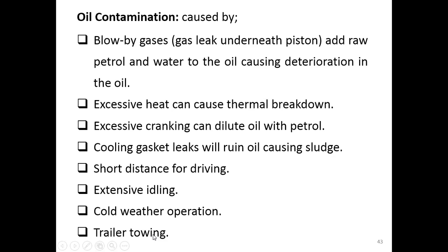And then we have the auto-lube system that is used for the two-stroke engine, where we have no space under the crankcase to store our lubrication oil. And then we have the splash system, where we have a dipper to splash the oil all over the internal parts of the engine to do the lubrication.